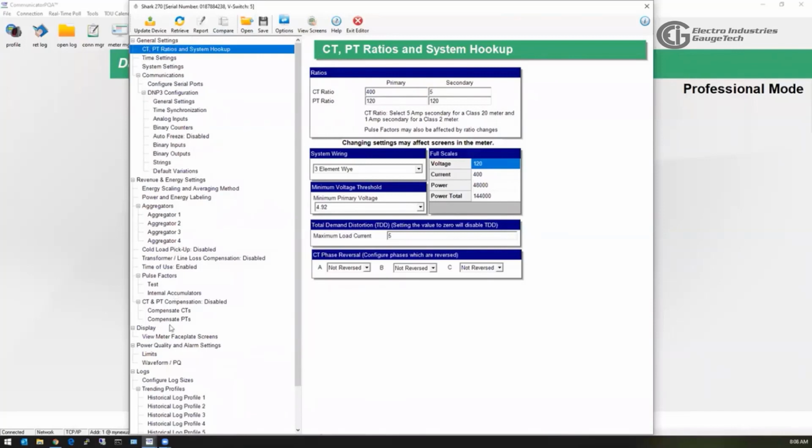There are many options. Don't be intimidated. This is basic programming. Your meter will function properly with our simple setup by simply putting in your correct CT ratios and PT ratios, 1:1 for Y connected.